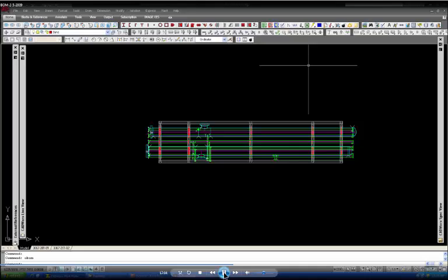A couple of things that I wanted to point out is that we could have isolated, run these bills of materials by line. That would allow you to actually run snapshots compared by line numbers. If you have a large facility with a pipeline that runs a long ways, then you can run a bill of materials just on a given line. You also can filter that way over on the filtering page.